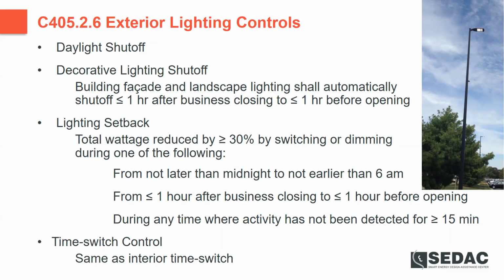So time switch controls do have to have the same requirements as the interior. Again, of particular note there is that 10 hours of memory. So in the event of loss of power, you don't lose your program for at least 10 hours. So that doesn't necessarily preclude mechanical time clocks, but we'll definitely see this going more towards digital time switch controls in the future.